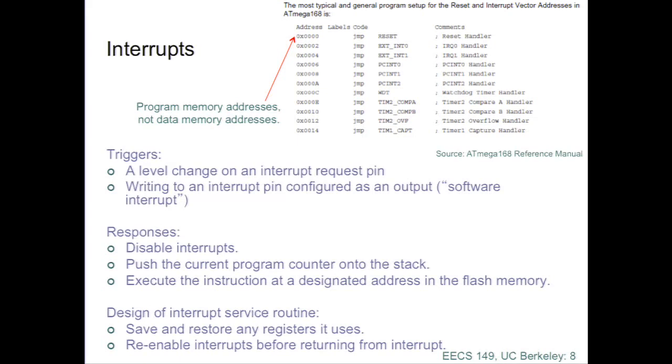The processor is being clocked, so in the next clock cycle, the instruction fetch will fetch the instruction at this address, okay? Then the return from interrupt routine will do the converse, right? It'll take the recorded program counter, load it into the program counter register, and that's all it does.